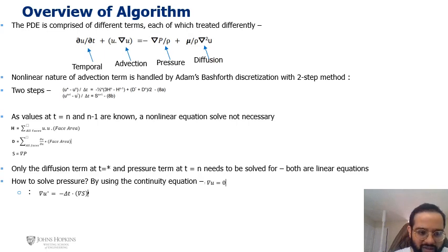And in the second step, un plus 1, which is the velocity at the next time step, is updated with this S value, which is the pressure term given here, the gradient of pressure basically. Now please note that I just wanted to simplify these equations for understanding, so I haven't included any of the constants in the derivation, but basically the d term is multiplied by mu by rho, and the h term is divided by rho. That's something that we need to know.